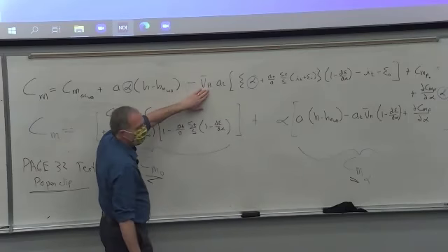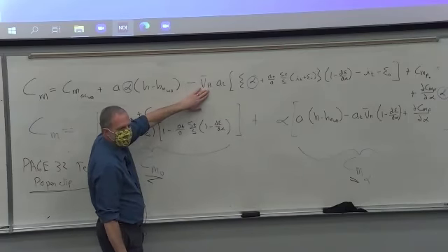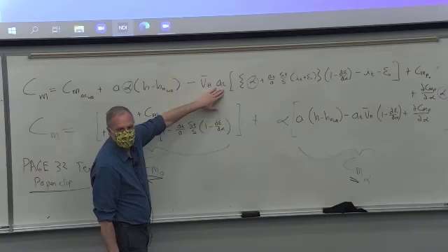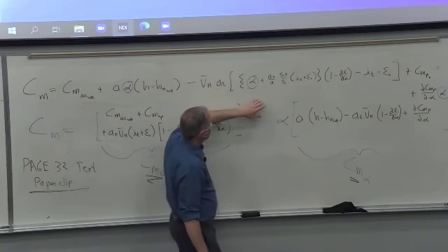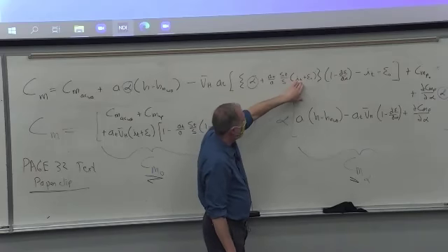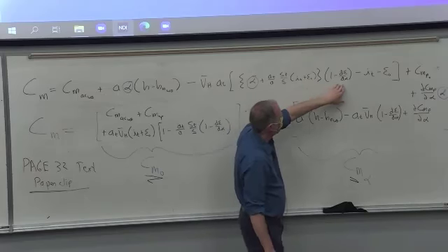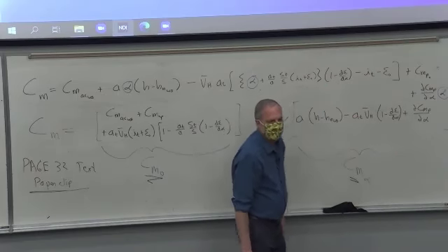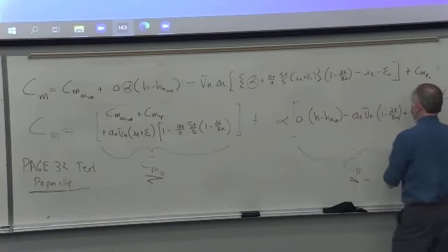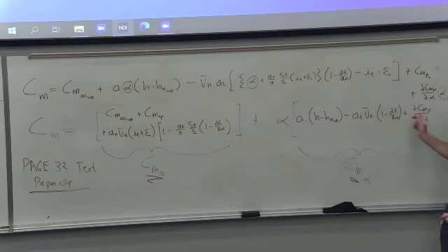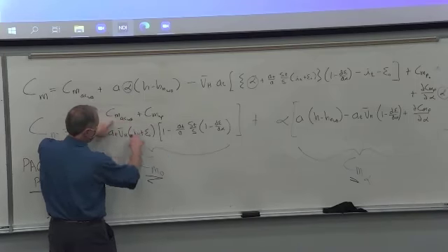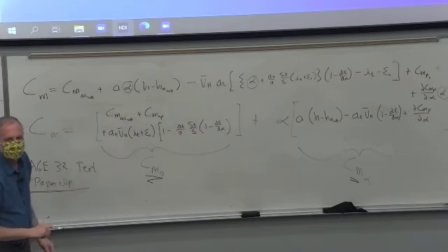We'll know the area of the horizontal tail and the area of the wing and where it's located. We'll know the lift curve slope of the tail because we'll use the big formula on that wing. We'll know the lift curve slopes here. We'll know the areas. We just talked about that. We'll know the angle that we set it at. We'll know the downwash model. So all of this stuff, when you calculate it, you just plug in all the numbers that we calculate in the locations, and so you just get a number here. And the same thing here. CM0 is going to be a number that depends upon the configuration and the geometry of the airplane.